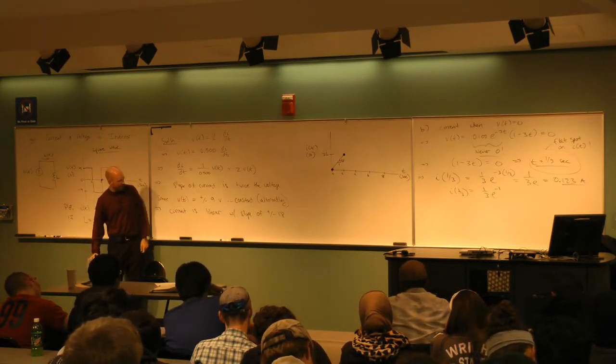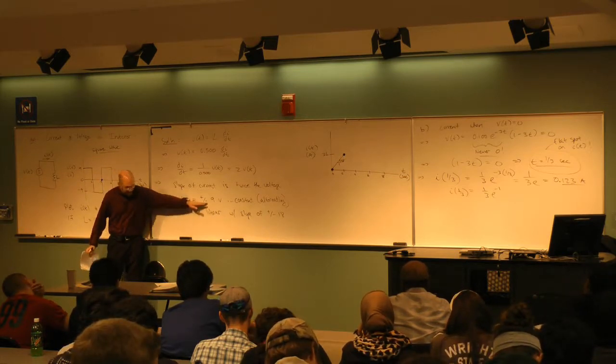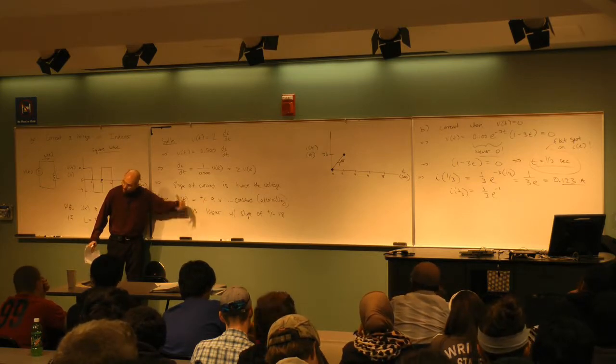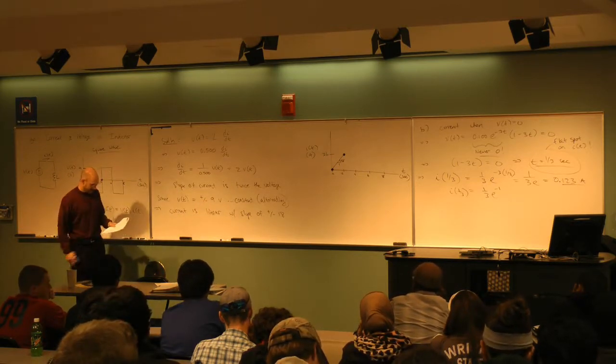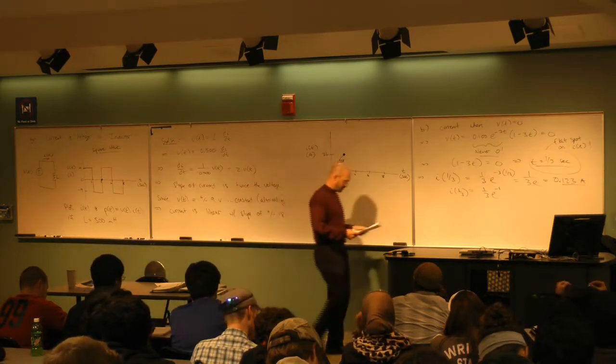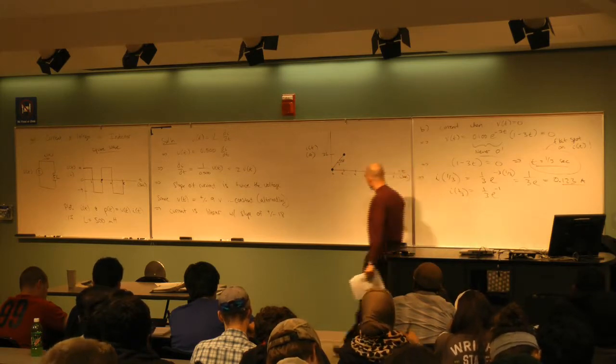So, again, that's the first interval, 0 to 2. I've got positive 9. Next interval, 2 to 4, V is negative 9 now. I of t is a straight line with a slope of negative 18. What do you think? Yeah.